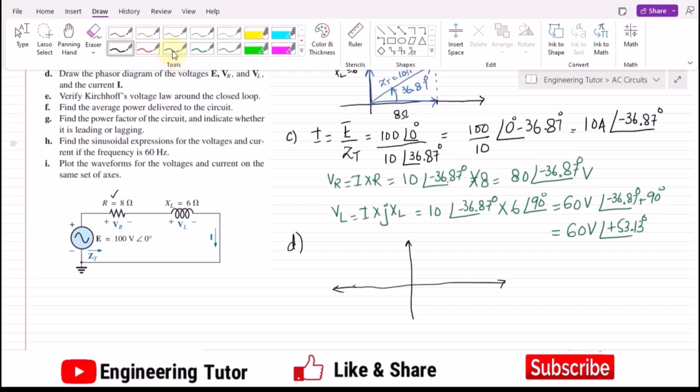Let me represent all the voltages with this blue. The first voltage is E, and the angle with it is 0, so this is 100 volts, and this is E with the angle 0. Now I have to represent the value of VR here, and the value of VR is 80 with the angle of minus 36.87 degrees.